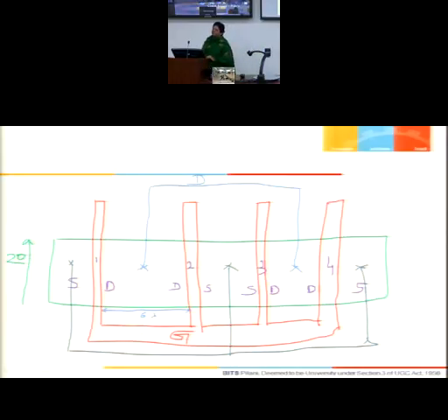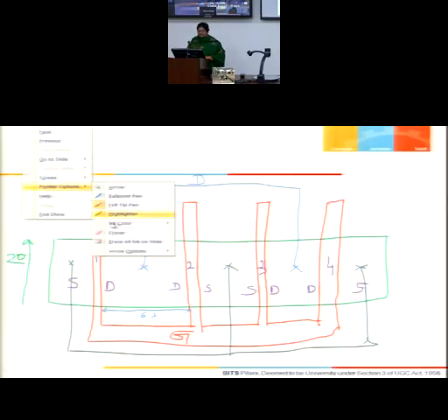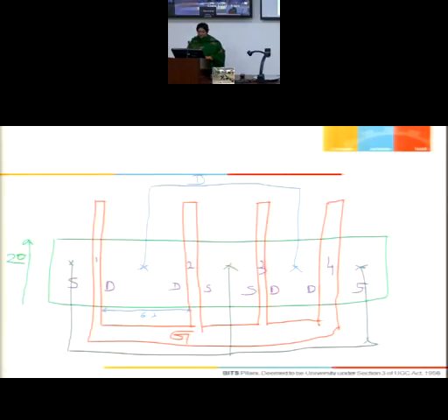So I have got now a multi-fingered gate layout of a big transistor whose width is 80 lambda and whose channel length is 2 lambda. Going by the design rules, if I look at this difference, it is going to be how much? Length? 2 lambda plus 5 lambda. So this is 5, this is 5 lambda. This is 6, this is 6, this is 6 and this is 5.